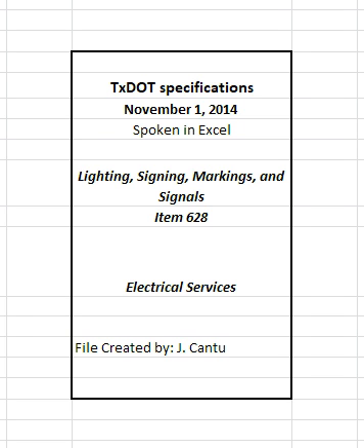3.2 Relocation. Coordinate relocation with the appropriate utility company before beginning work. Remove existing electrical service according to removal under this item. Reinstall existing electrical service according to installation of this item. Replace or add circuit breakers as noted on the plans.